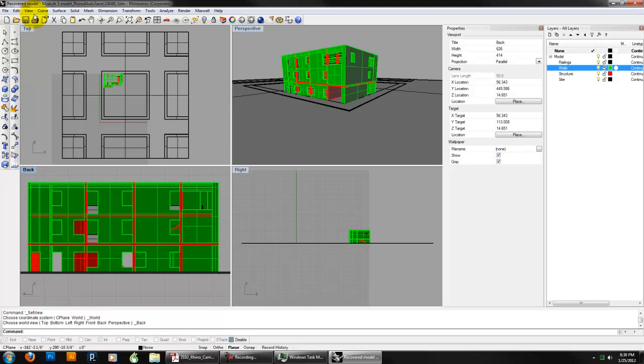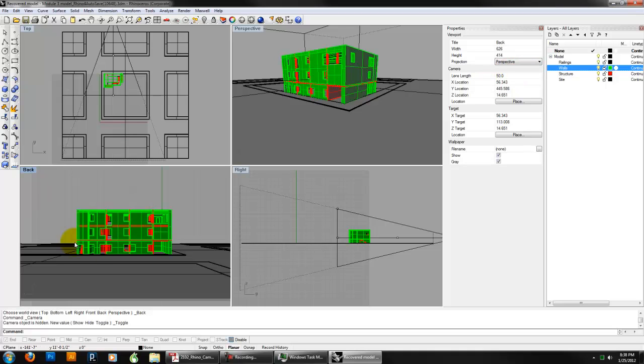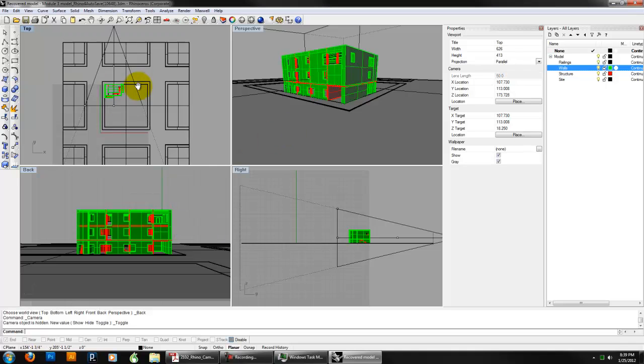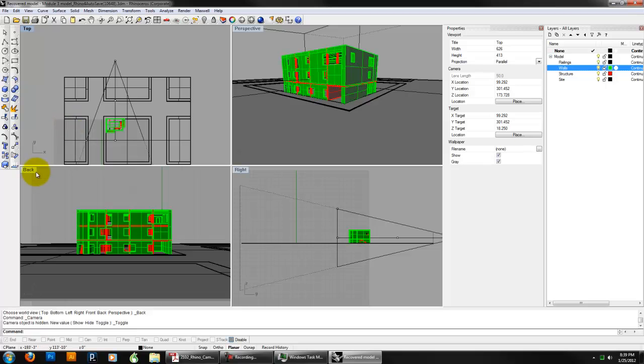Go to the back, turn on the camera, so I can do F6, and you can see my camera. And you can see that the camera says it's parallel. I'm going to change that to perspective, and you already begin to see the vanishing point in this, right? So I went from a view where all the lines are parallel, there's no vanishing point, which is orthogonal, to a perspective for that back camera. And you can see that I have a camera now in my top viewport.